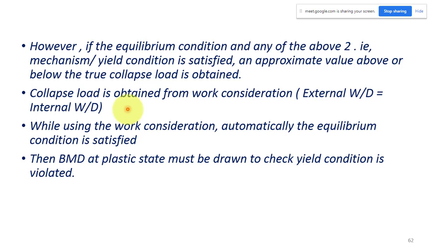While using this work consideration, you have automatically satisfied the equilibrium condition, since in the energy principle the forces must already be in equilibrium. Apart from that, we have to draw the moment diagram at the plastic state and make sure that the bending moment at any section does not exceed the plastic moment.